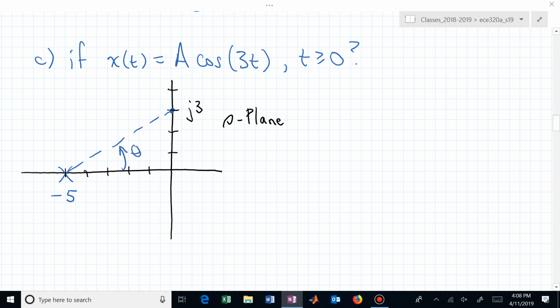That's now the angle theta that this pole factor is contributing. And we also have this length, L. You could figure out the magnitude and angle of the pole factor with the overall by just evaluating H of j3, your transfer function at that particular location on the imaginary axis, which is j3.